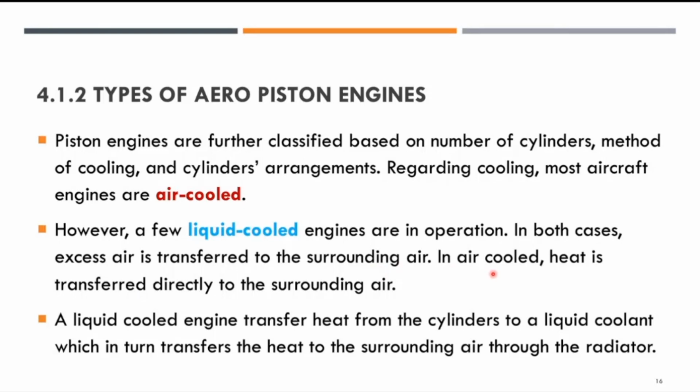In air cooled, heat is transferred directly to the surrounding air, whereas a liquid cooled engine transfers heat from the cylinders to a liquid coolant, which in turn transfers the heat to the surrounding air through the radiator. So there is another part here where we require heat being transferred to the liquid, and then the liquid coolant will be transferring heat to the surrounding via the radiator.